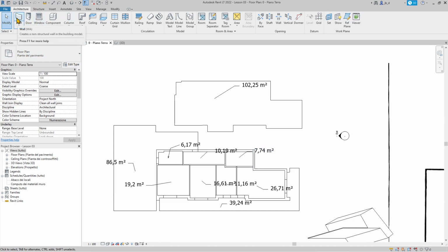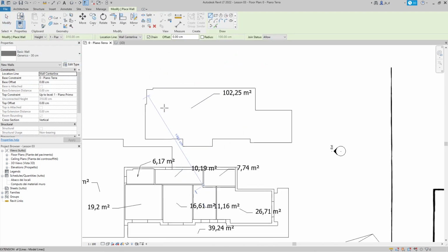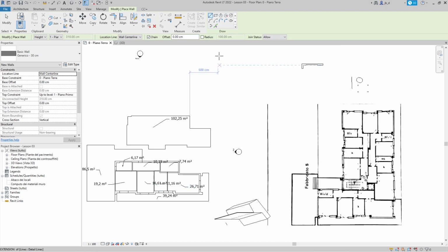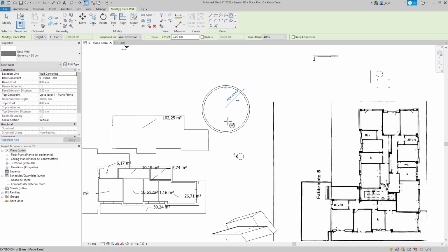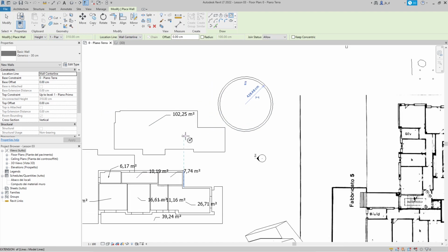Now the easiest thing you could probably do in Revit is create a wall. So let's click on wall, and we will just go there and start to draw. Now you can see that creating walls is just like creating 2D shapes or 2D drawings, except that we're going to create a wall. So you can use a line, you can use different shapes. For example, if I use a circle, now I can create a circle, but that's not going to be a simple circle. It's going to be actually a model, a 3D model, something that's right there in your project. Could be a circular room.